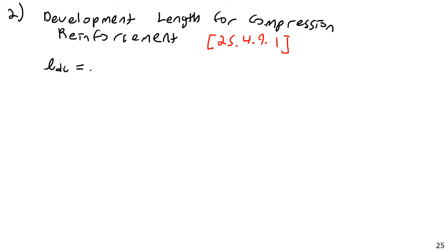Again, like I mentioned previously, sometimes you'll have compression reinforcing when the concrete alone is not able to carry all the compressive loads. You could just use a deeper beam, but then your weight increases. So maybe you're very limited in the physical dimensions of the beam you can use, so you'll add compression reinforcement to beef up the strength of the beam.